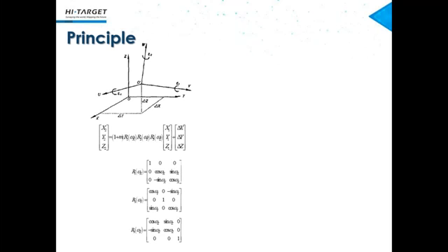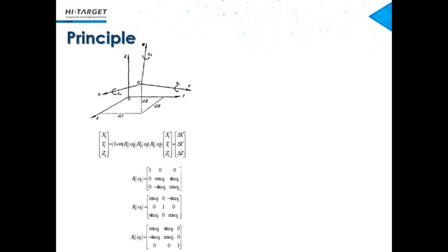So in these pictures, you can see that it should move in 3 directions, because we need more control points to calculate the parameters. If you only have 3 control points, you may not be able to verify the accuracy, whether the parameters are calculated well or not. So I suggest you use 4 or 5 control points to calculate the parameters.